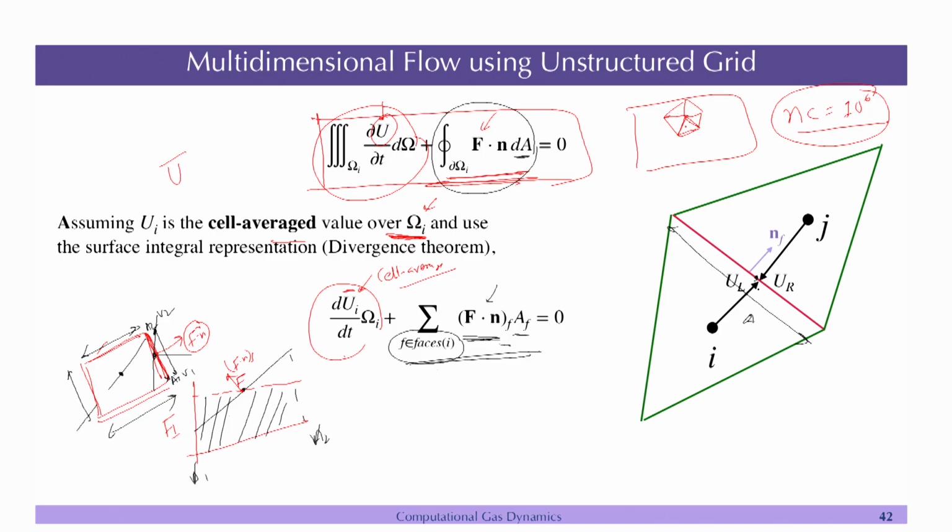Okay. So, this is a nice representation of two cells, which we call I and j, and there is a normal which is calculated here, going outward, and all these normals and everything have to be calculated in the beginning itself. And the calculation of the normal is very important, because if you do not calculate it properly, then you will have issues in running the code. And you have to follow a certain direction.